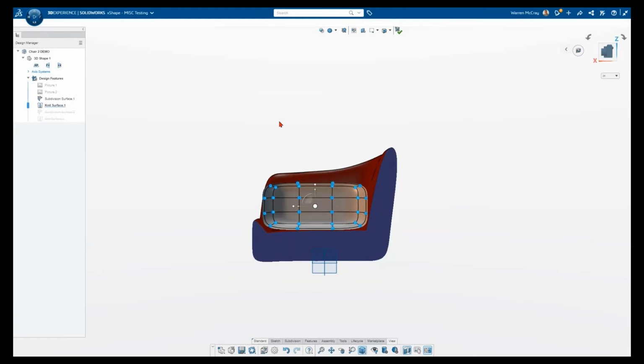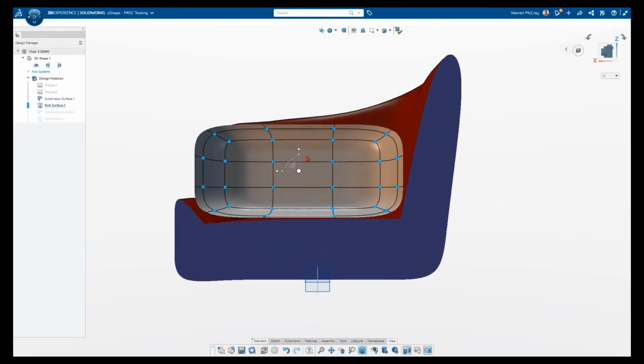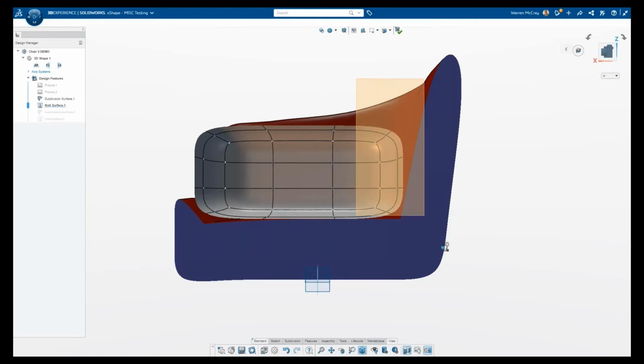See, you could do this. This is easy. And now I'm only working on this primitive. See, when this primitive is active, I'm only working on this primitive. If I Windows select all the vertices, I move the entire primitive. If I select only some vertices, I can adjust, move, and rotate just the ones I have selected. If I want to pick certain edges, certain vertices, I can pick them, drag them, and move the edge just a little bit.